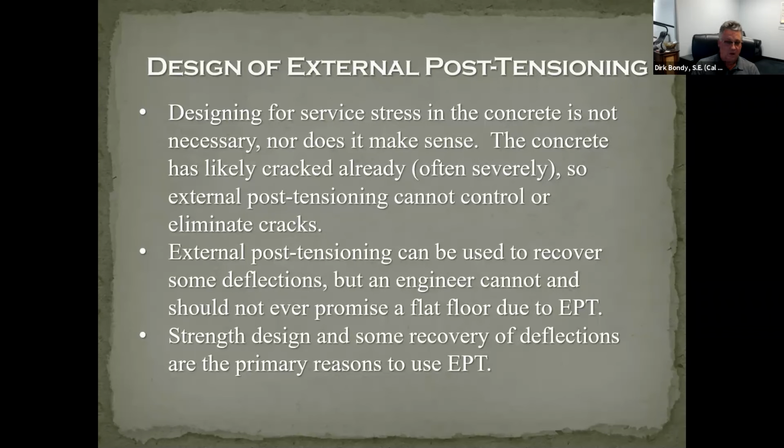Now, we can recover deflections, but never ever promise a flat floor due to external post-tensioning. You never understand the properties of a severely cracked system well enough to know how it's going to react. You can promise some recovery of deflections, but if you need a level floor, use leveling material, like lightweight gypcrete, something fluid flowing that can give the architect, the owner, and the tenants a flat floor.